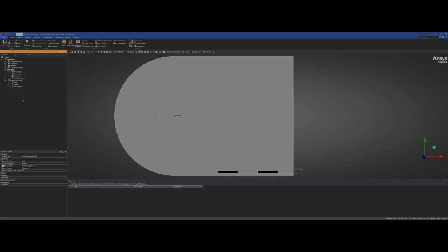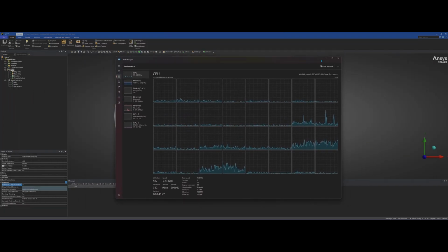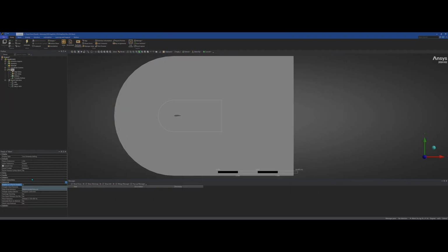Now we're not going to start meshing yet. I'm going to mess with this. So we're going to go 0.0125 right there. And then in advanced, this is important. In advanced, I'll set it to 32 because I have that many cores. So you see right here, I have a pretty powerful computer. But this depends on your computer, so that'll be up to you. Now we're ready to run. So I'll click generate.